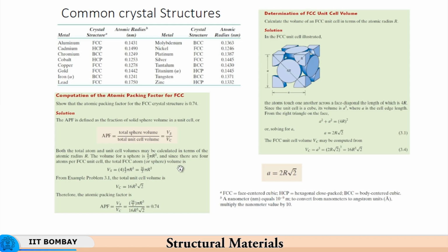So, basically what it means is that the structure is responsible for the kind of unique properties the material has. Body centered cubic materials include chromium, iron at room temperature particularly, tantalum and molybdenum. Tungsten is another body centered cubic material. And most of the high temperature materials, refractory alloys, are usually body centered cubic materials. That is something that is noteworthy.